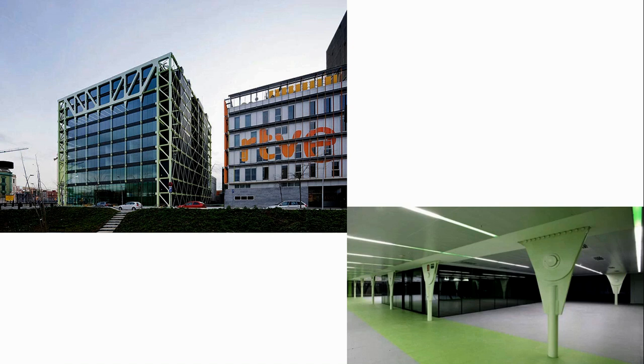They're the same thing happening again. Interesting building, the ICT Media Center. Look it up if you want to, if you have a look at it. Here it's really clever, very obvious, isn't it? Here we've got a bridge, here we've got the big truss connecting to the two ladder trusses, we call these, on either side. So even the walls are kind of vertical trusses. And here's the tensile rod that's carrying the floors, isn't it?